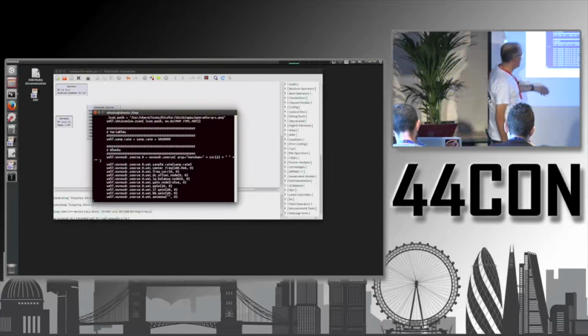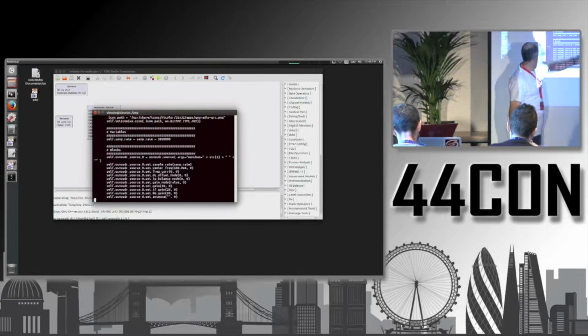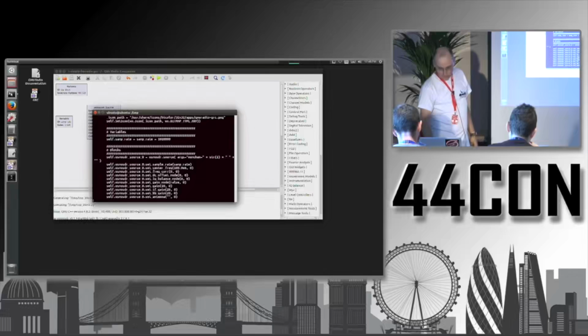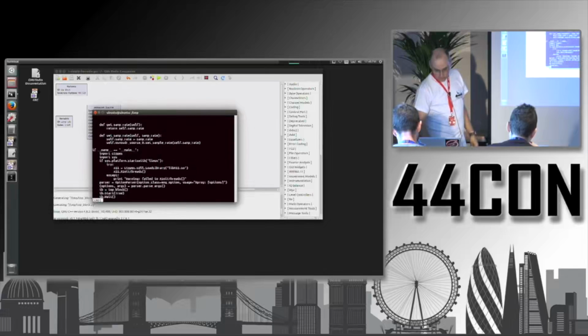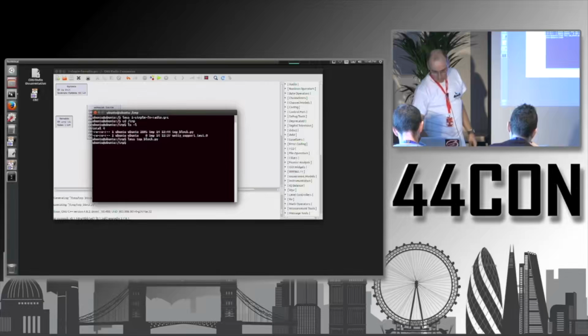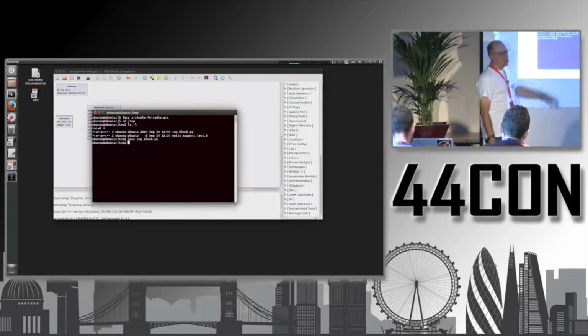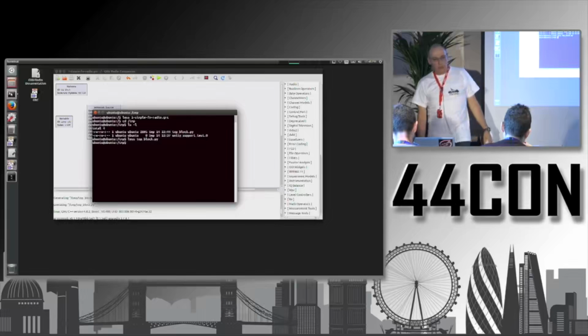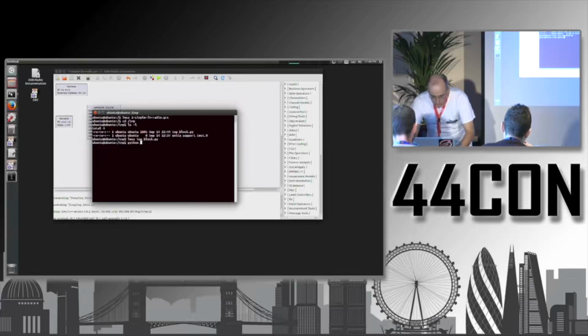And here, for example, you can see the frequency that I set. You can execute this program too from Python. You don't have to run it inside the GNU Radio Companion environment. You can just run it from Python like this.